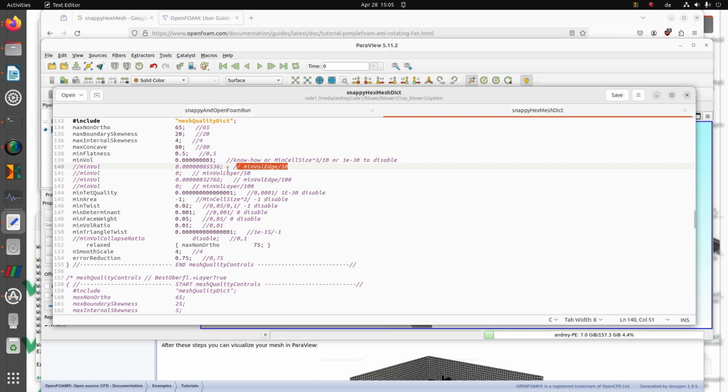This definition should be preferred. If we take minVol smaller, as it is defined in know-how, the calculation will be cancelled, no matter which other settings are used in the mesh control. The minVol definition is essential.